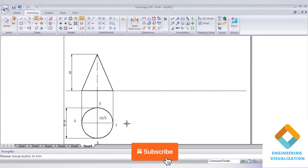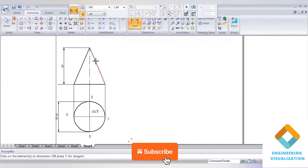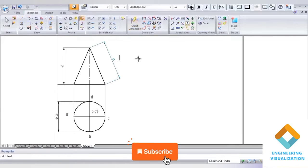So this is drawn with the slanted length, so we don't require a parallel line here. You can show that slanted length, that is capital R, 65 mm. You can mention the slant edge, capital R is equal to 65 mm, and small r, that is the radius, is 25.